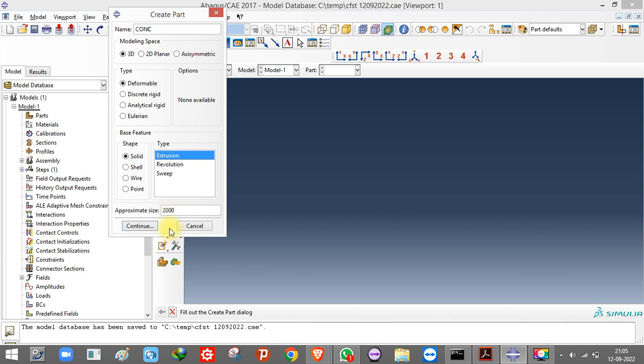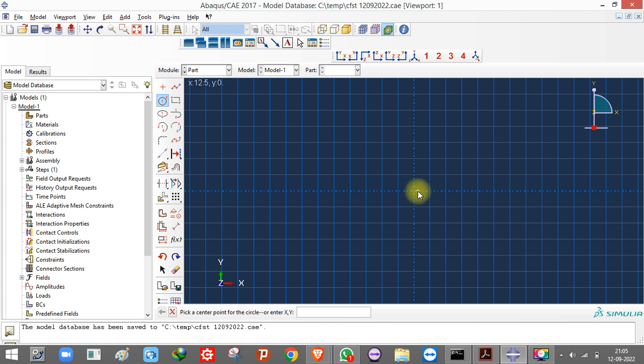Now we'll work in mm. In mm it becomes easier. So see, while making this circle, you just cannot click like this to end the circle. Always make sure that you start from the center and you are clicking on either of the axis, because the point where you click will be your junction joint for this circle.